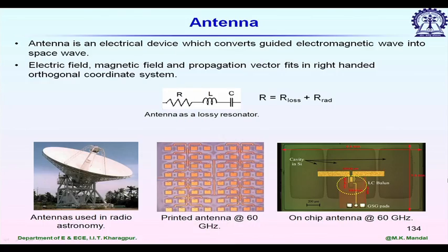When we do so, we of course face some problems. You can identify there are some cavities. This particular antenna is designed on a silicon substrate, and in silicon we face the problem of surface waves. To avoid that, people use an air cavity just below the antenna, which improves the gain of the antenna.